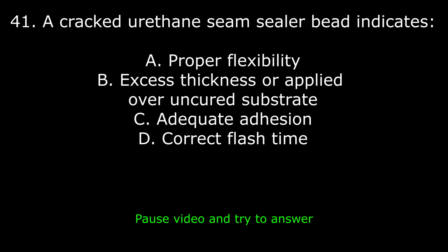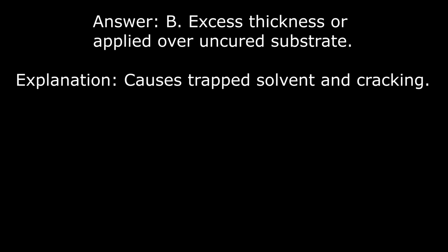41. A cracked urethane seam sealer bead indicates A. Proper flexibility. B. Excess thickness or applied over uncured substrate. C. Adequate adhesion. D. Correct flash time. Answer: B. Excess thickness or applied over uncured substrate. Explanation: causes trapped solvent and cracking.